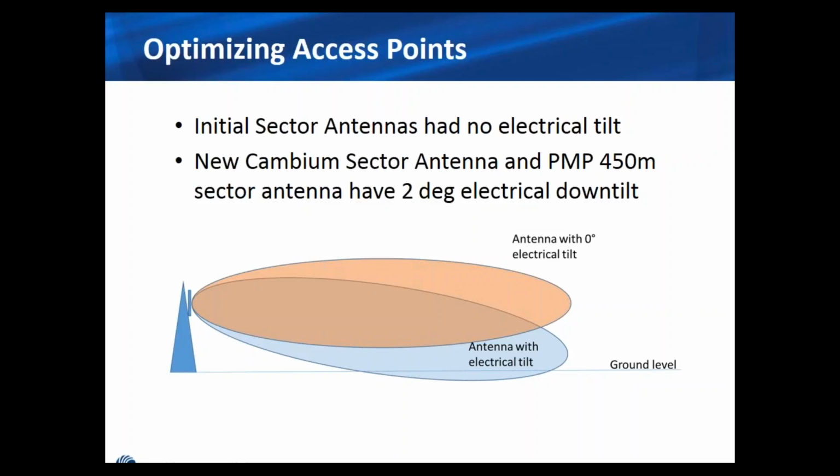As this simple image shows, if you mount the antenna so that the back of the antenna is vertical, with no mechanical tilt, the peak of the beam is no longer parallel to the ground but is already pointing down towards the ground by the amount of the tilt. This means that when planning with these antennas, you need to take care about the tilt angle that is used.